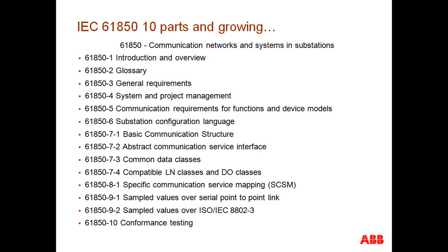And then we have part 7, which really dives into the data model and how we are going to model information within the substation. So in a nutshell, the data model parts discuss the introduction of the logical node concept, as well as the pieces of information that are part of each one of those logical nodes, and the format of those pieces of information.